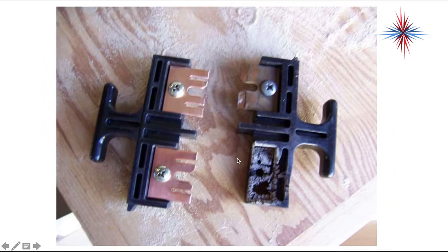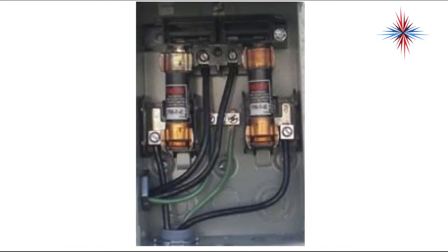Here's an example. The normal look is this, and over time, weather will start getting to them, and it could actually pull out and leave one side of the terminal in the system. So you do need to check with your meter even after you pull these out to make sure it has actually disconnected. This is a fuse type. Your pull-out that I just showed you goes on the top here, and then there's a fuse on L1 and L2 that protects the equipment.